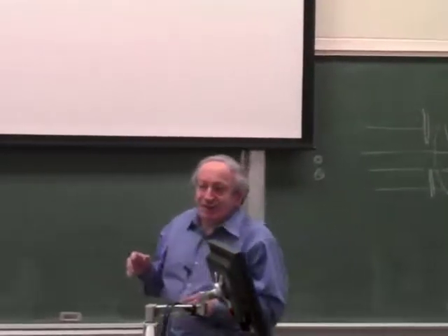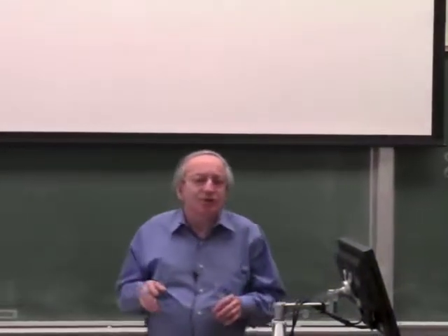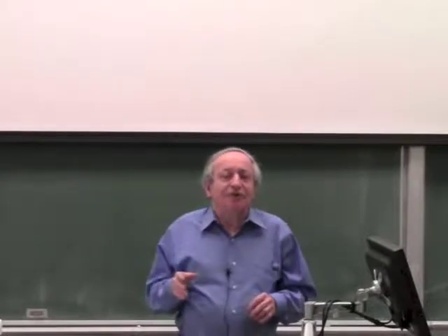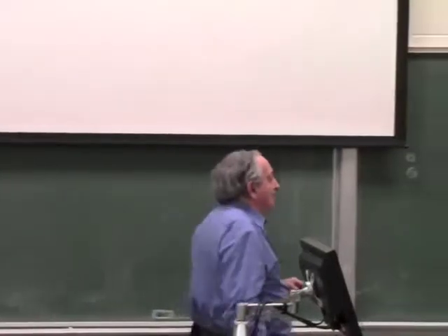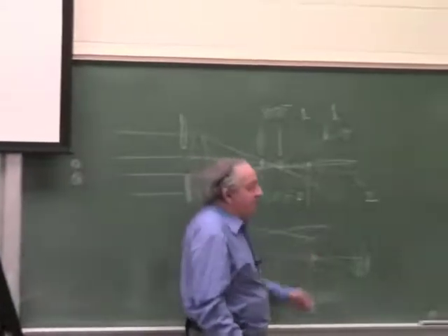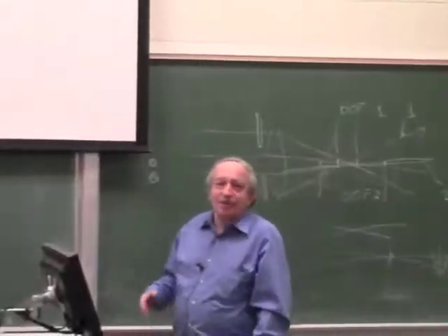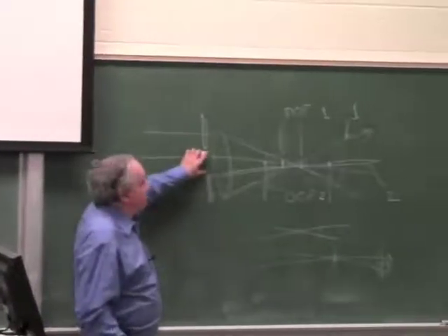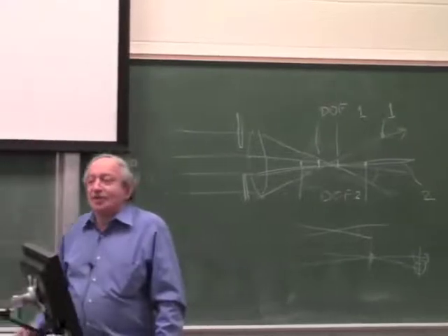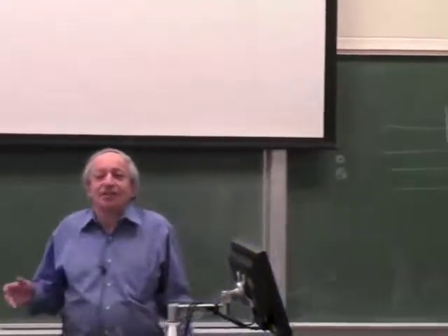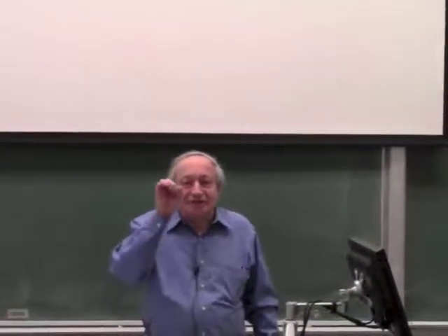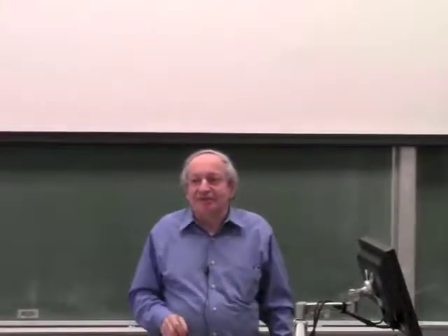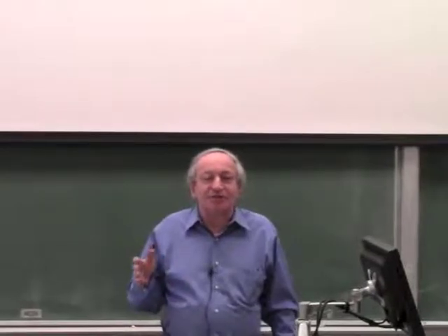So when you stop down the lens, the light goes down, but that's usually not a problem with CCDs. CCD cameras are very sensitive. But so far I only said good things about stopping down. The depth of field or depth of focus becomes much bigger, aberrations become much smaller. Technically the lens is much cheaper if you only have to make a small lens. So now I'll ask an opposite question. Why aren't all the cameras made with a very tiny aperture, in other words a very large f number? Because so far I said so many good things about stopping down.